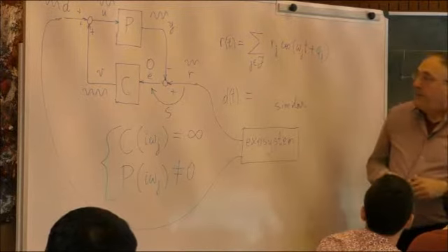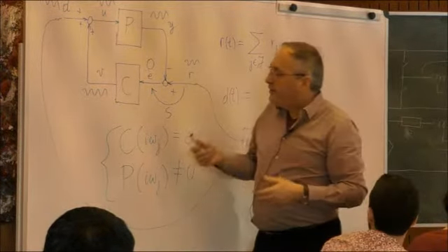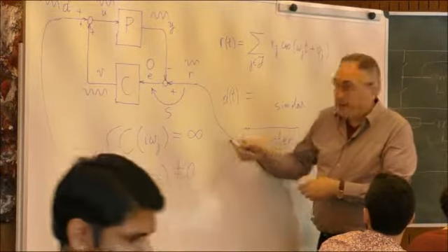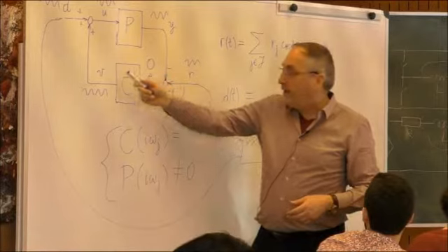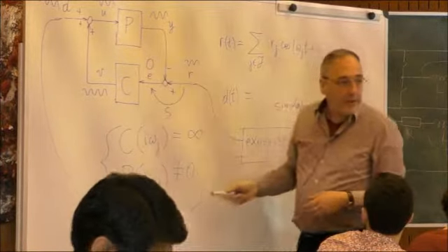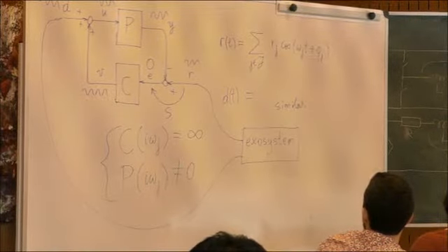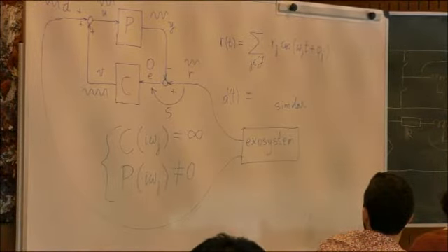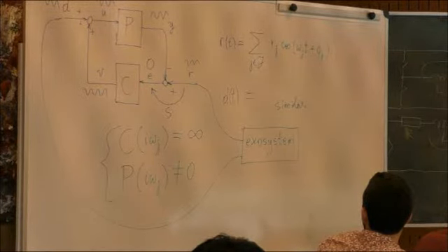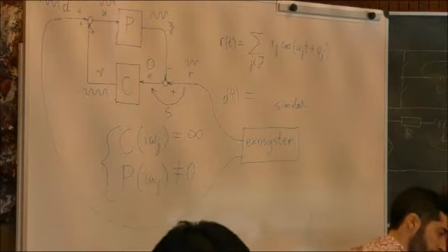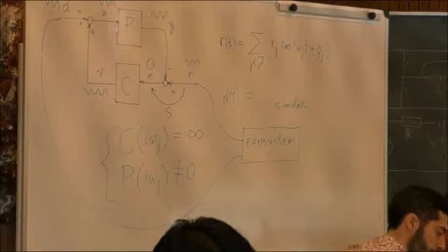And now we realize that in steady state, the controller can also generate the same signals, right? We just said it receives input 0 and it generates the same signals like the exosystem. So that means that the controller is an internal model of the exosystem. The exosystem is an imaginary system somewhere outside. We don't see it. We only receive the signals from it. Yes? And the controller is able to generate the same signals on its own without any input like the exosystem.